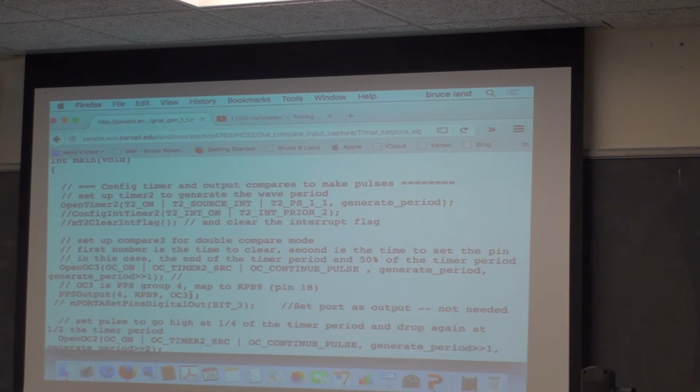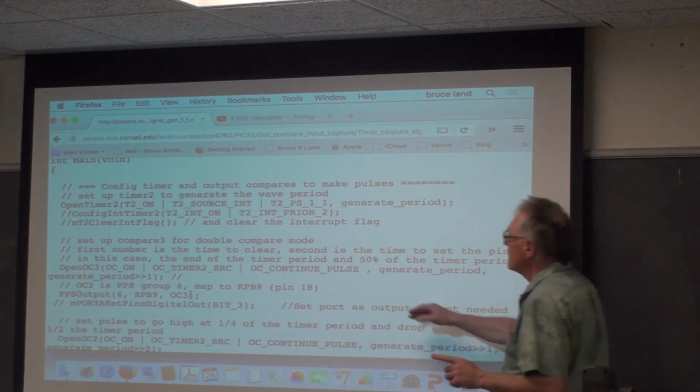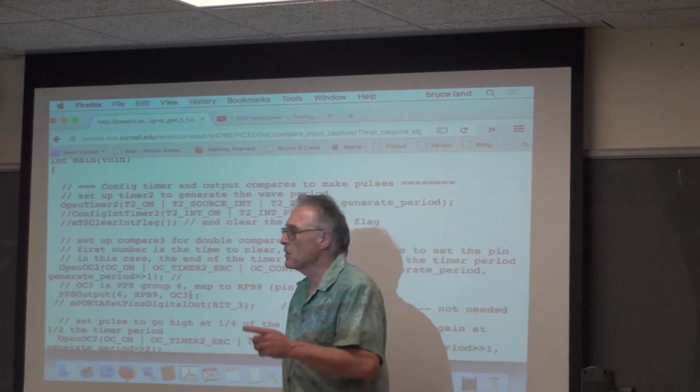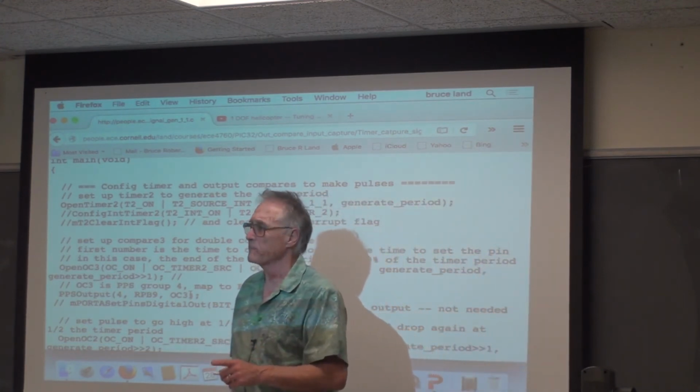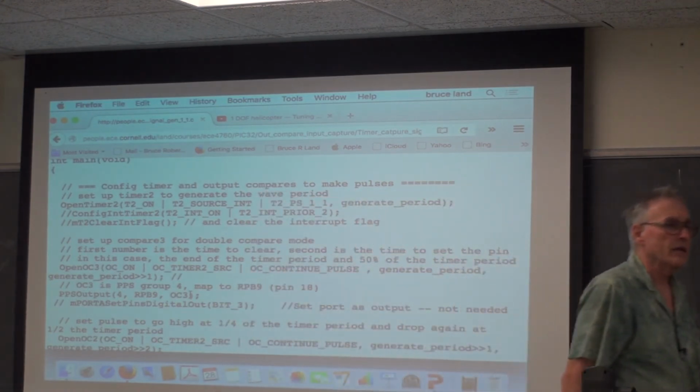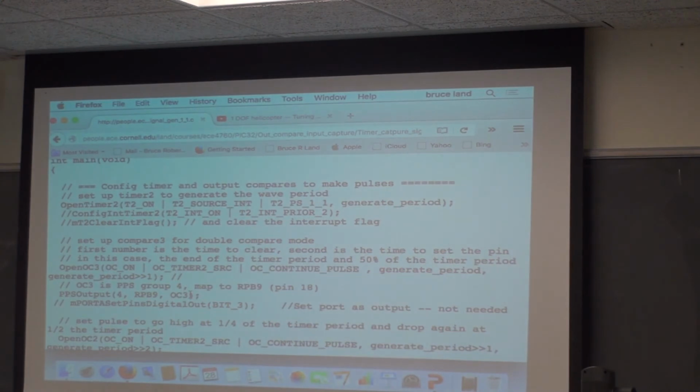Now, if you go through this and say, he must have been full of it, I'm going to uncomment those. What will happen? This causes a really obscure error. And that is because you have initialized an interrupt for which there is no interrupt service routine written. And the behavior of that is undefined.